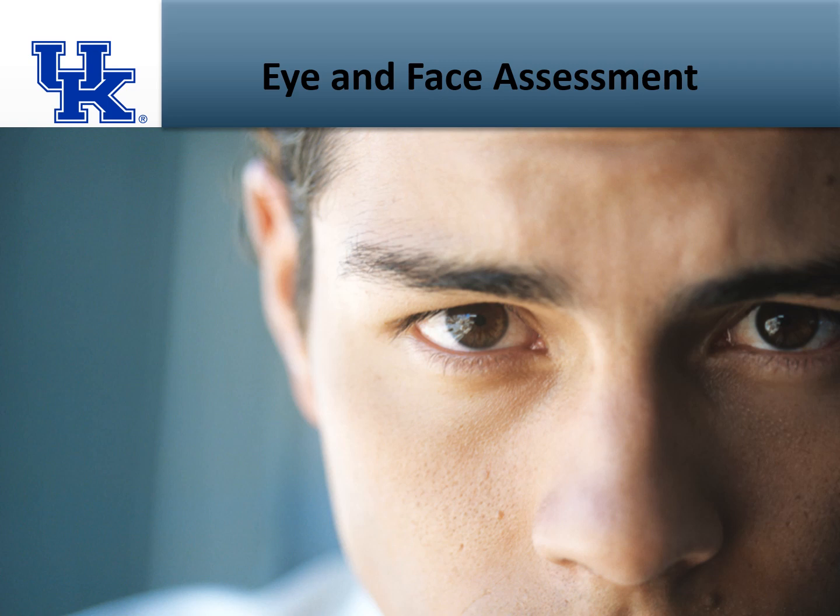Hazard assessments are conducted to protect each part of the body. Let's start with the face and eyes. Your employer checks for exposure to flying particles such as dust from grinding, metal chips from machine shop equipment, or wood chips from a cabinet shop. Fine particles cause the majority of eye injuries in the workplace.